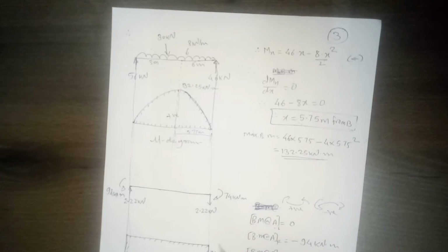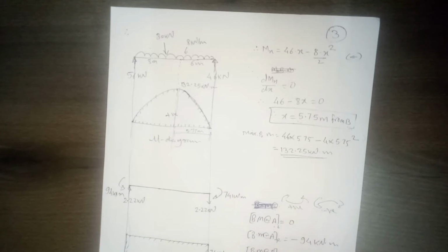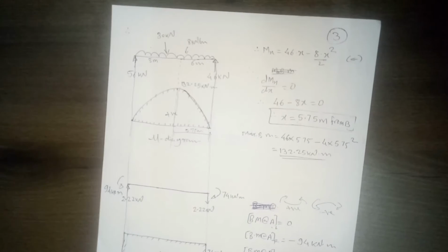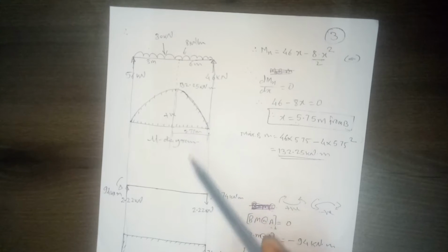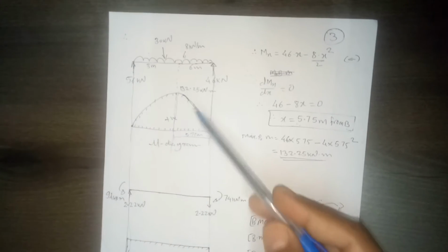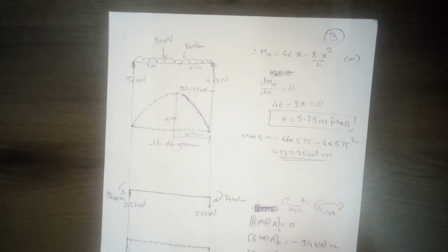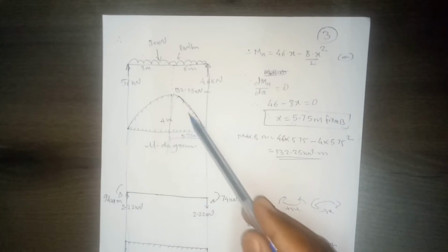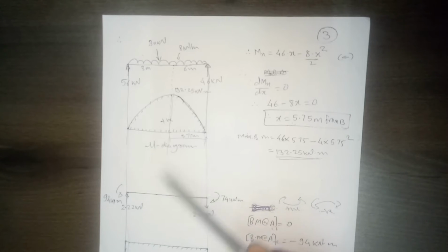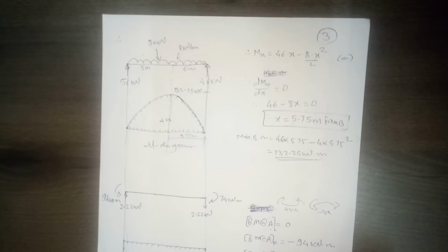Though we are not using one principle here, just for your information, for this Mu and Mu dash diagram, if you calculate the total area of the positive and negative moments, then it should be the same. Though we are not using this principle now, to solve some other problems we may derive the fixed end moment this way, and in that case we use this principle. First, the area of the positive Mu dash diagram and the area of the negative one are equal.